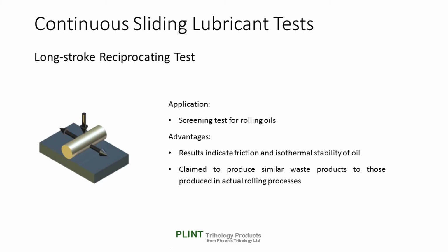The temperatures for aluminium and copper rolling are higher than for steel and zinc, and a very important consideration here is to identify whether essential metal soaps can be formed once the temperature of the tooling and the workpiece exceed the working temperature of the mineral oil. This point is identifiable by a change in the friction forces.